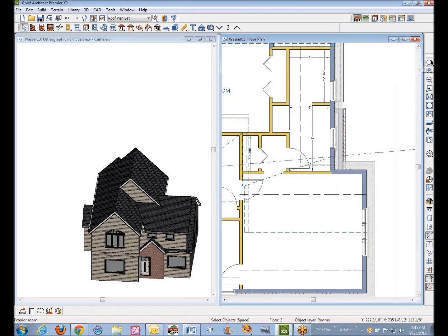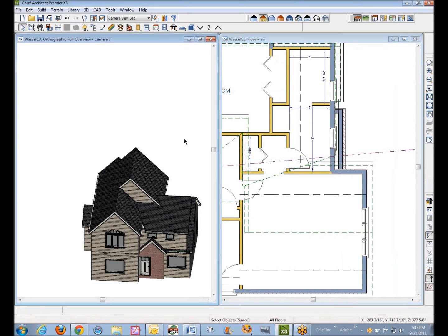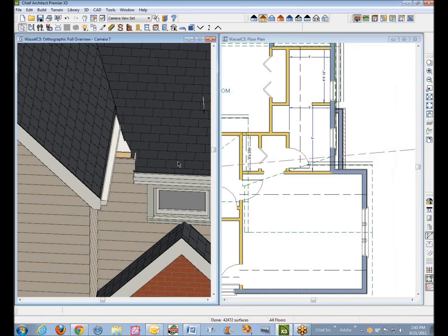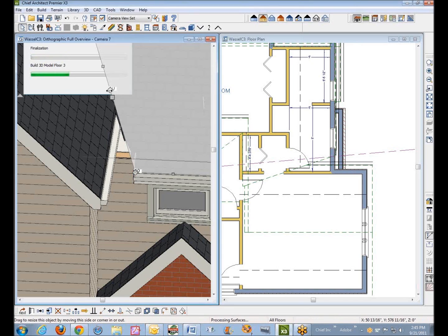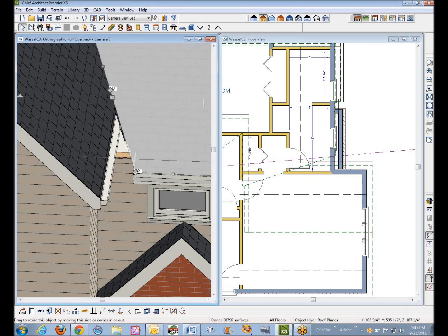Well, okay. I can't find it in plan view. I suppose I eventually would. I'm just going to zoom in over here and see if I can't do it in 3D. What I'm looking for is to chop it along this wall here where my cursor's moving with the break tool, up right along in there. That'll allow me to hinge this over like that.